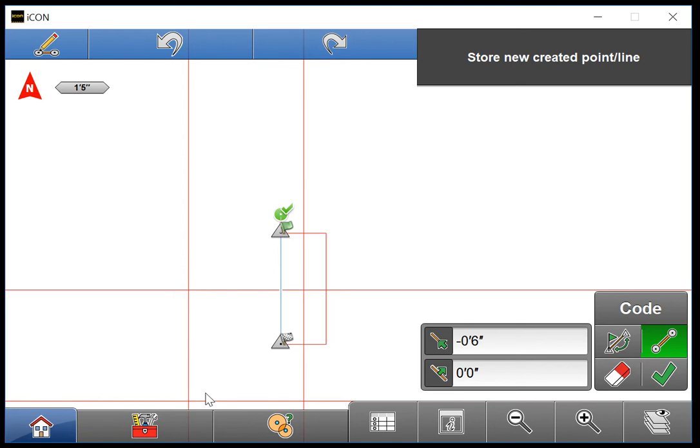The box below station is offset. I can go either left or right of line. Notice that the symbol shows an arrow pointing away from the line perpendicularly. Let's go 6 inches right first.